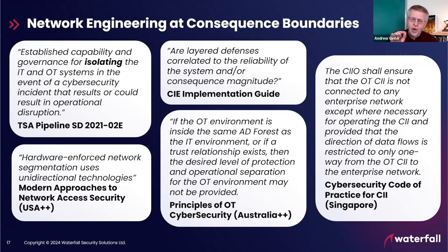Why is that important? All cyber attacks are information. The only way a control system can change from a normal state to a sabotage state is if attack information somehow enters the system. And so, whereas on IT networks, information is the asset, we try to protect the information. On OT networks, information is the threat. Information is the way that attacks enter. So again, the requirement is one way out, nothing back.